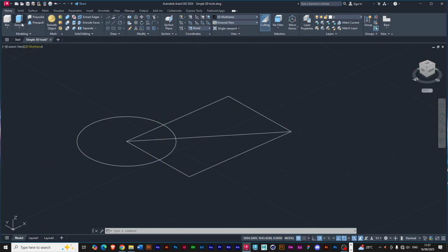Okay. So yesterday I described the difference between an extrude and a press pull. I said generally an extrude extrudes out a complete shape. It doesn't cut off, like this circle, for instance. If I click extrude, it will pick either the rim of the circle or the circle itself. If I pick this rectangle, it's going to pick the rectangle, and if I pick this line, it's going to pick a line. So it's not going to cut the selection; it's going to pick the whole shape itself.